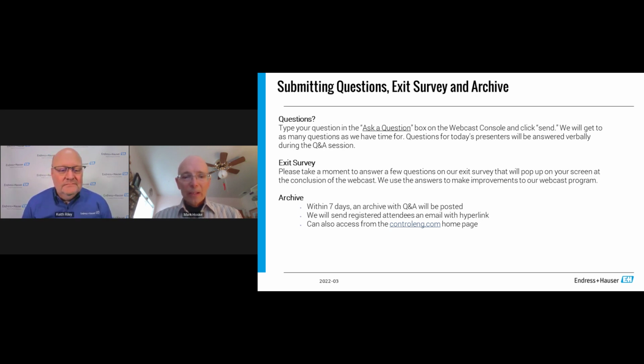Great. Does the asset information feed into our existing control system or asset management system? That's going to be a bit conditional as well. Obviously, as you've heard, a lot of the monitoring device information can be shared over a HART variable, but if you're not using a HART card directly on your measurement, it's going to be more of a manual upload into the asset management at this time.